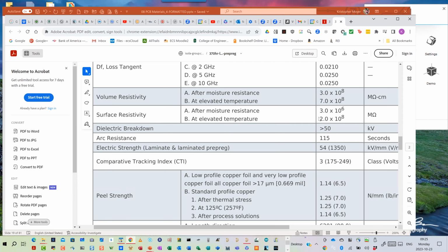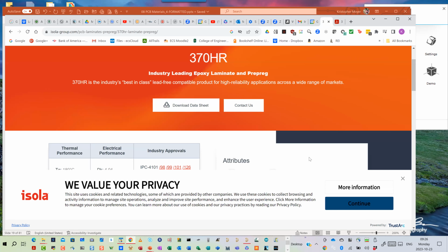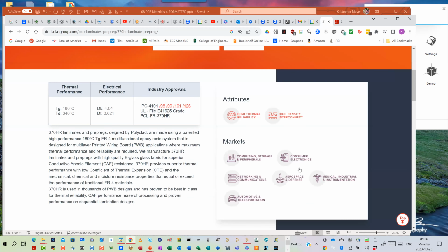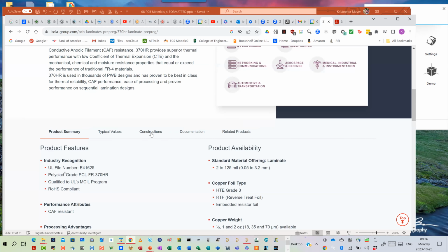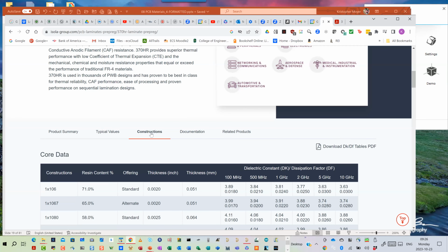So the slash sheet is a starting point minimum, but this is why I said previously, in constructions, at a minimum, specify all the parameters you want. Exactly what dielectric constant, exactly what electrical strength, dissipation factors, and so on. Now, I'm going to point out one more thing, and I may have shown you guys this already. We'll go back over here. Not only does the master data sheet have a difference of parameters and performance over what we see on the slash sheet,